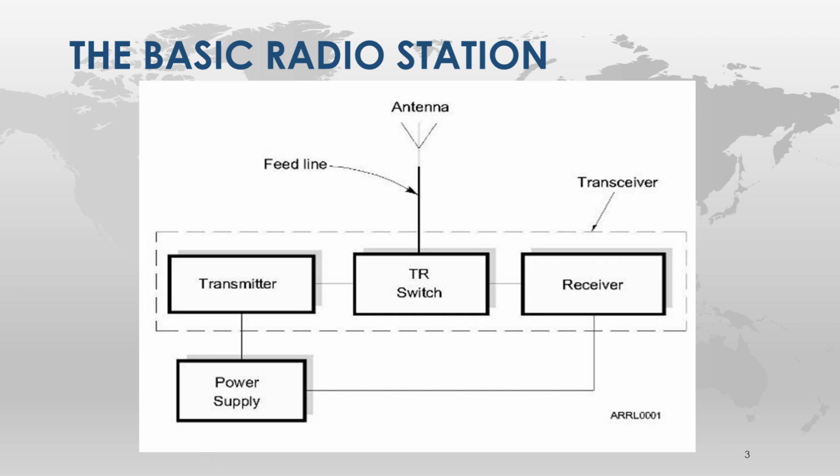Yeah, so with a repeater, we've got filters. We call them cans, but you're receiving a signal and you're transmitting a signal at the same time. And so we've got a system in there to separate those signals so you don't blow things up. In the old days, you literally threw a switch when you wanted to change it. Now you just let off of the button and it does it for you on everything I know about.